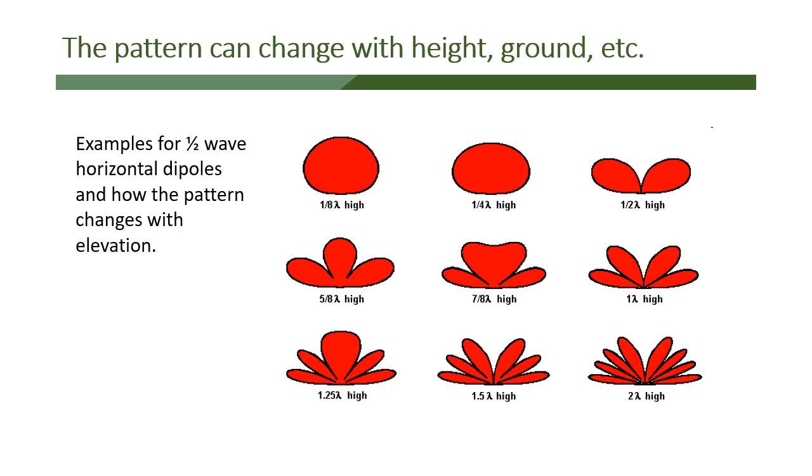However, with VHF, most of our operation is FM in the technician class, not so much SSB and other modes. We're vertically oriented, so we're using space wave and ground wave, not sky wave. These patterns are really illustrating sky wave, but for space wave it's really just about one thing: the higher a VHF/UHF antenna goes, the better it is for line of sight.